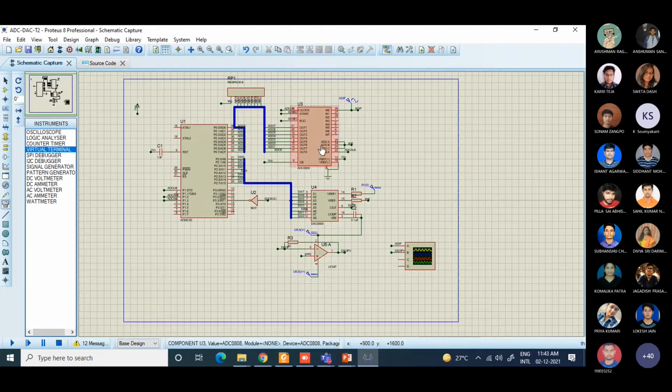But at the same time, you want to know what is this input signal, this measured value, right? And so from the control room, which is far apart from your place, this local means the local region. So this DAC will work with the control mechanism or control circuit, which is analog in nature, for example. So your analog controller will be controlled by this DAC output locally, and you want to observe from the control room what is this measured value of this input signal. This can come from a sensor, right? The input to the ADC.